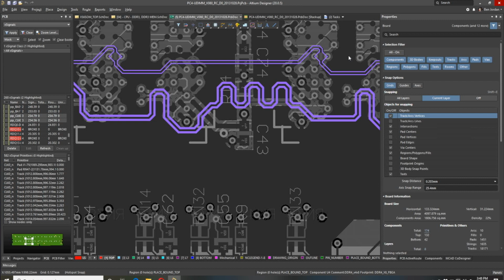Yeah. So we think of grids for placing parts because when we came out with the radial grids, for example, I did a marketing video and I showed placing LEDs in a row around a circular placement, and the grid was a nice, easy way to do it. But it's actually a really critical tool that you can use to accelerate fan-out and manual placement of vias and things. So let me show you that. There's another design I've got here.